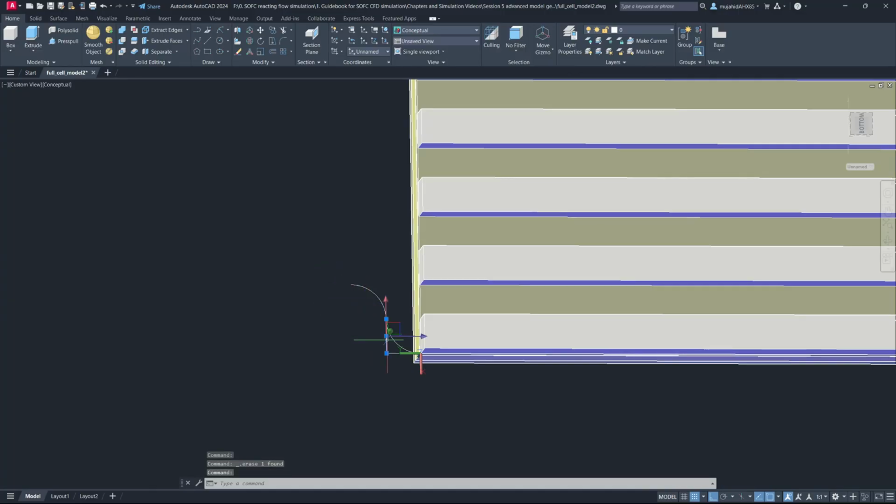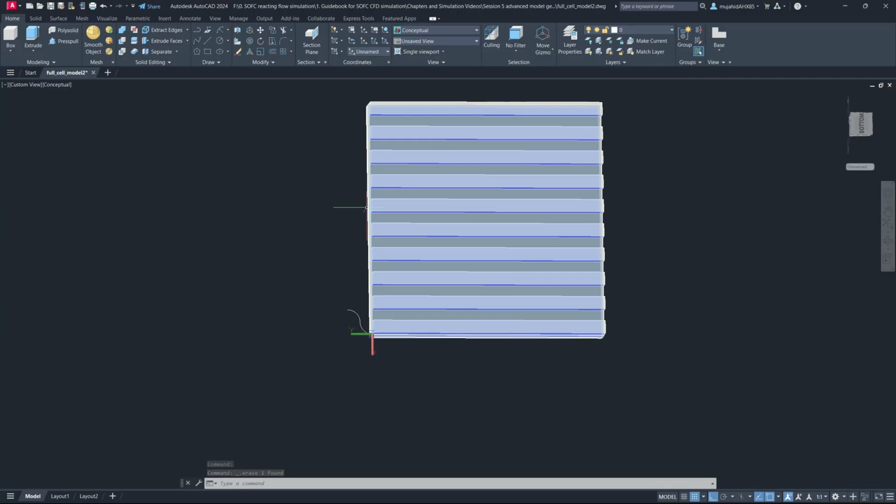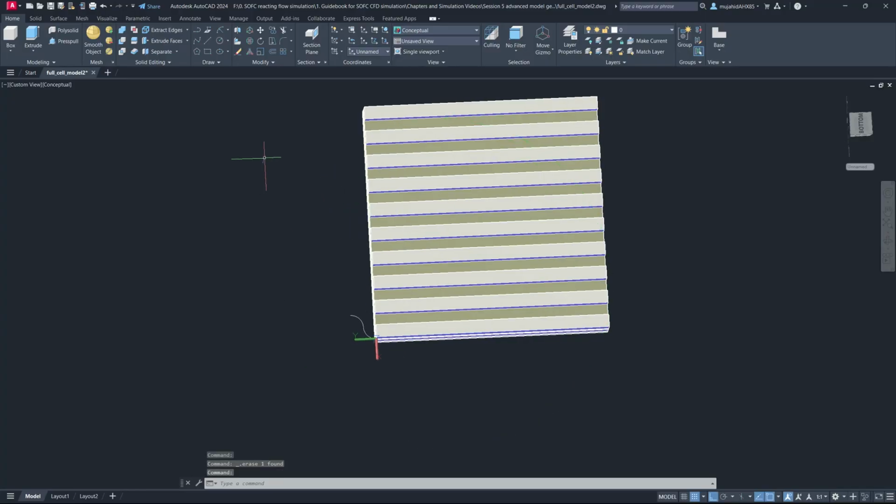Delete the lines. You can add a line, so you can shift this origin. In the x direction we want to move minus 9.5 because this is half of 19 mm, sorry, 9.5, and we will add a line over here, that this should be a construction line.